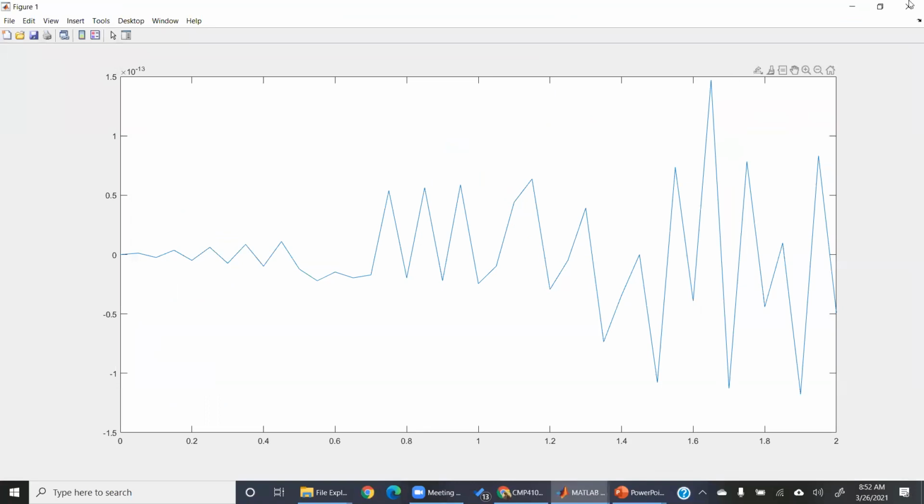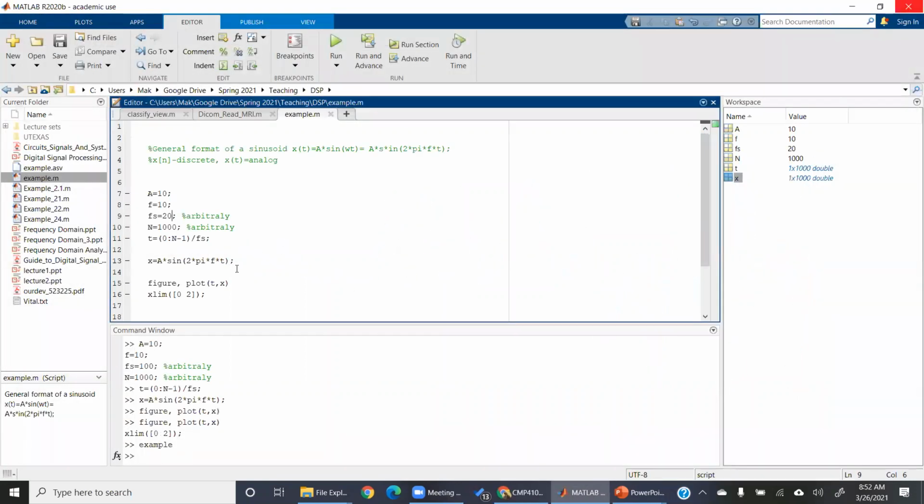So this is what I was telling you about the Nyquist sampling theorem. You see, they tell you at least twice for you to be able to recover anything. But to recover the signal in its entirety, you should actually go as high as you can. So the fact that even when we had 100, you had some information missing means that 100 is also not good enough. If we made this 500, and remember, this is digital signal processing.